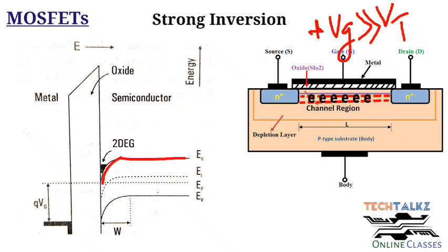If you check the energy band diagram, due to this sharp bending at the interface, more electrons will be trapped here. Since the electrons are trapped, the electrons' movement across this direction is also confined or restricted. So the movement of electrons is confined within this potential well.